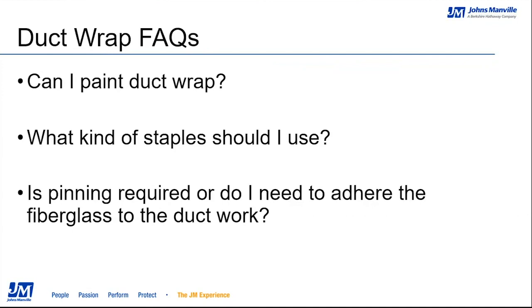If you start gluing that together, you're going to start compressing that fiberglass down, and there's a real good chance you're going to end up going past the R value compression that you're really looking for. So you want to be careful when doing both of those things, and we do have several technical bulletins that you can reference that are available through our technical line if you need that information.